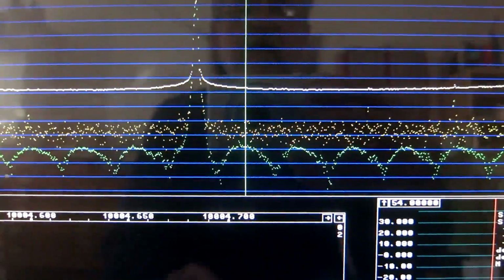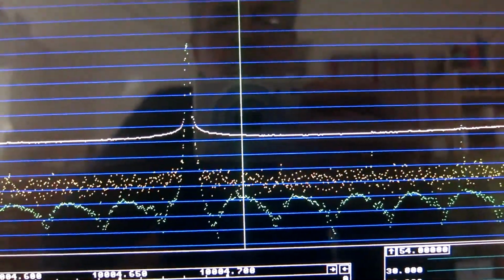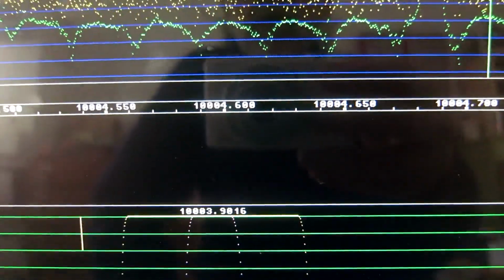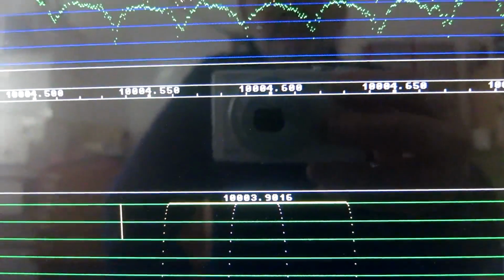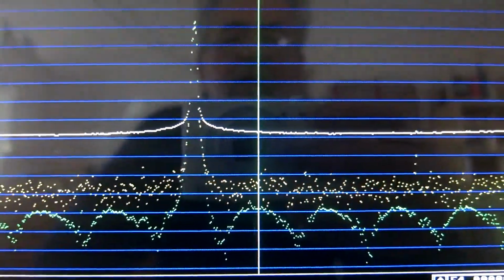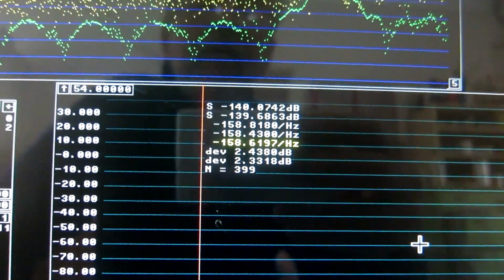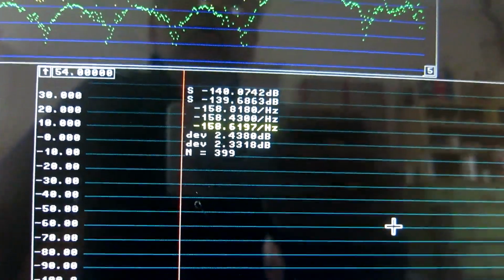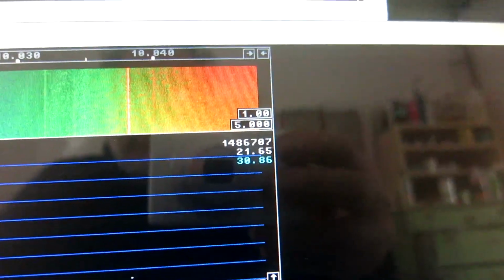I have disconnected the Schottky mixers and replaced them with dummy loads. I have set the frequency now to 4 kHz from 10 MHz, where there is a peak in the correlated noise. The summed power is -158.6 with a correlation of 21.6.